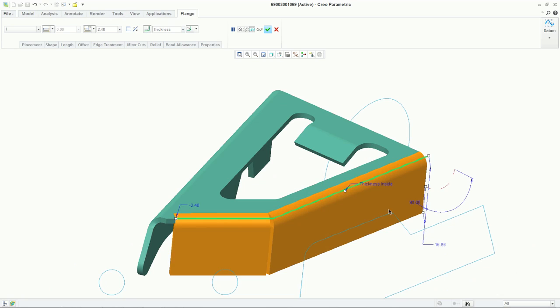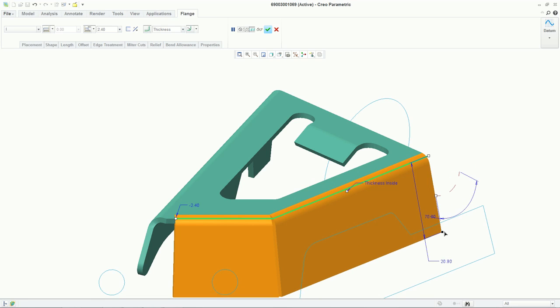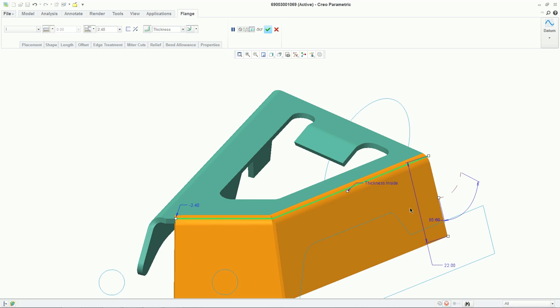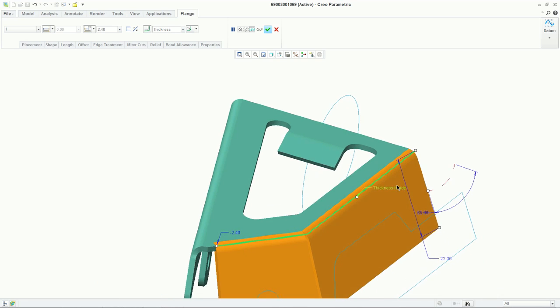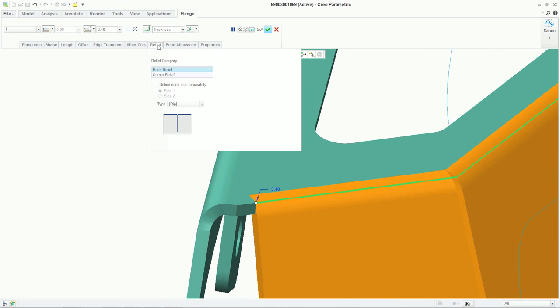As we create the feature, Creo provides a fully regenerated preview of it properly intersecting the part. If the user sees the fully regenerated feature, they can be confident that it can be created with its specified parameters, and they can make changes to the feature as other design ideas are explored. The user has the option to drive default tool values by sheetmetal parameters or not.